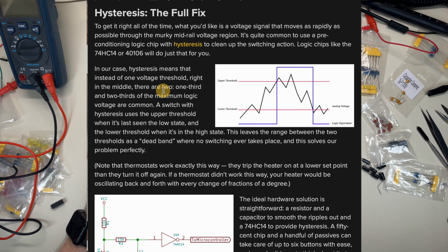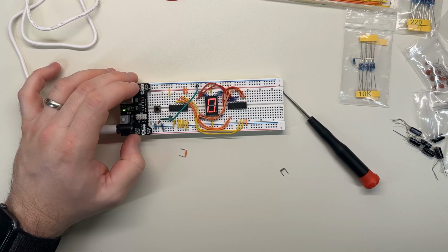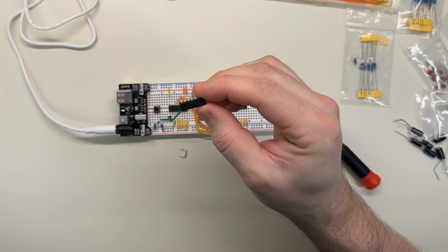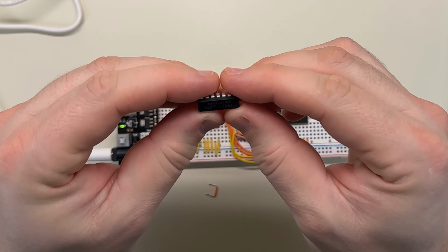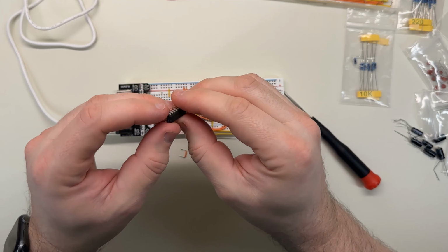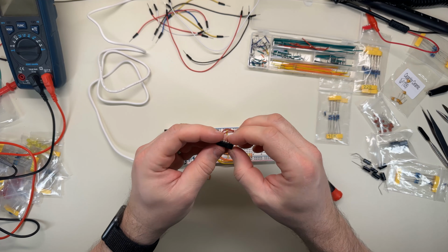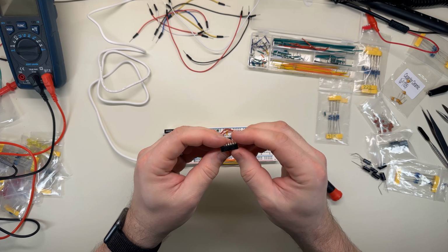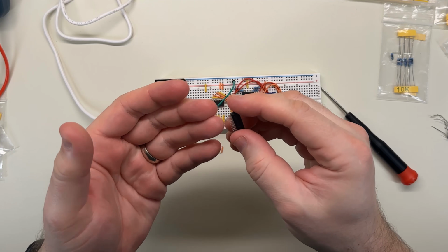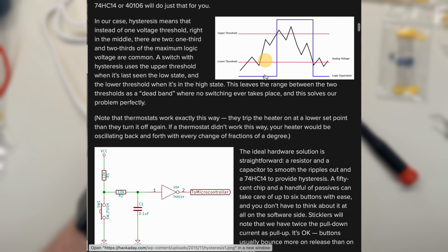And it turns out that there are logic chips that have this in them, and this thing is called a Schmitt trigger. And I actually have one right here, in the TTL kit that I use all the time: an SN74LS14N is a Schmitt-triggered hex inverter. Hex inverter just because there are 6 of them, but also because it inverts, which is kind of curious. So you put a signal in on one of the pins, and then the output is actually the inverse after it's been thresholded like this.